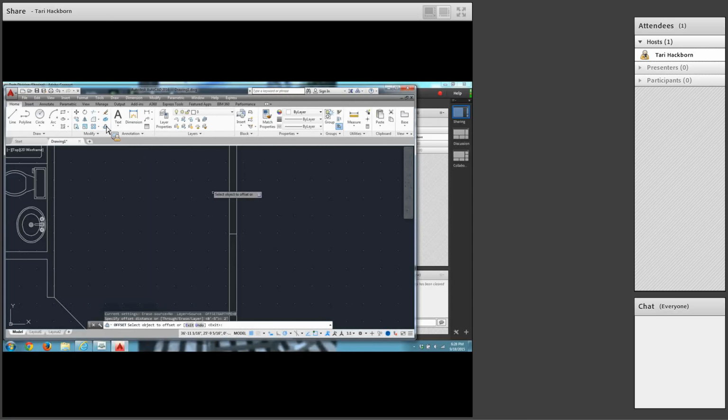That's one way of doing it anyhow. Click up and down. Sometimes when I click up, I also click over a little bit, just so that an O-snap doesn't pull it way up to the end of that line or something like that. You don't need the middle line, so erase it.